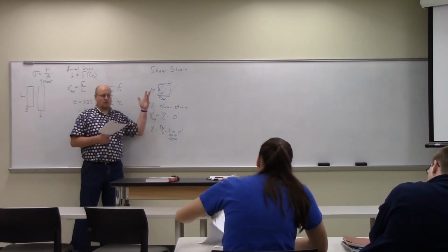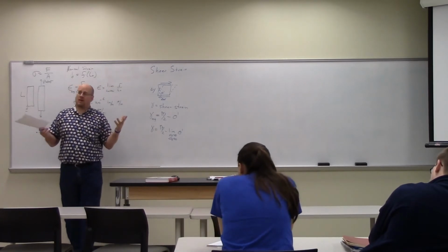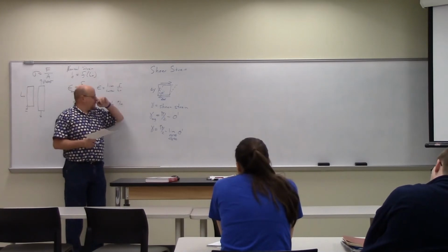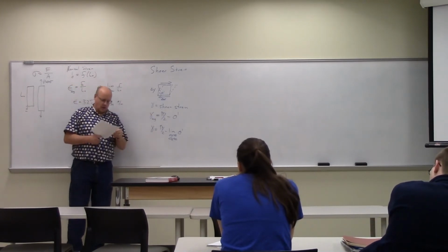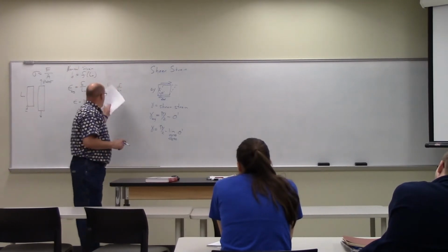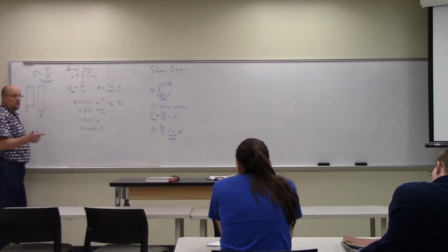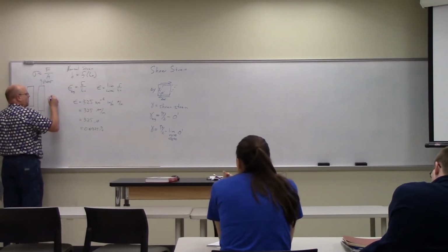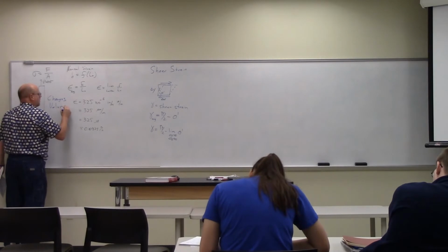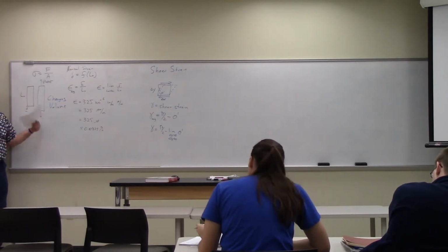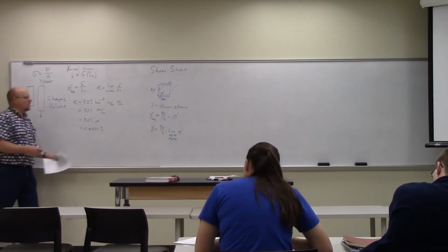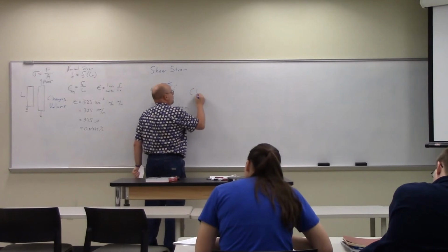So shear strain is just an angle. Shear strain has units, if you will, of radians, but radians are not really units. You guys know that, right? So it's effectively a unitless quantity, just like normal strain is. Whereas normal strain changes volume, as Blake pointed out. When we divide out the area, we get the volume. That's where we get the element from. If I pull on the thing, I make the volume bigger. This shear strain changes shape.